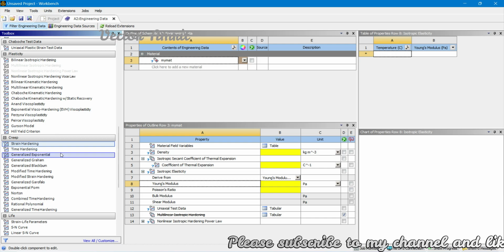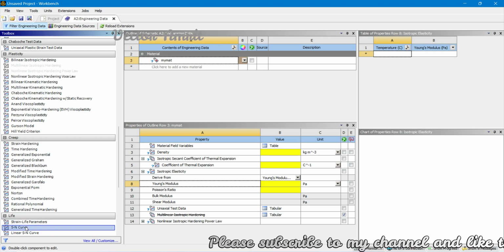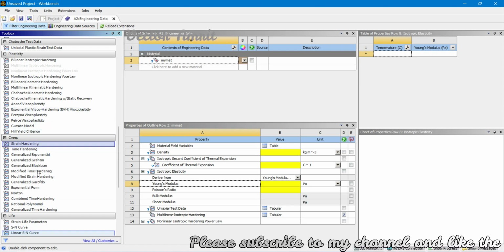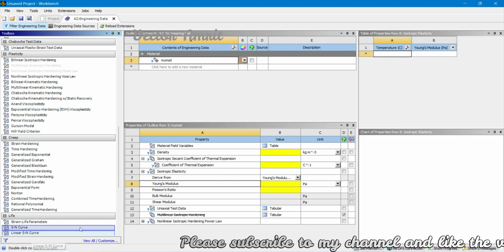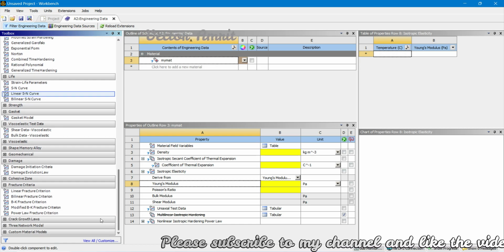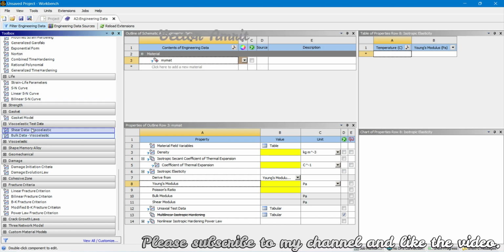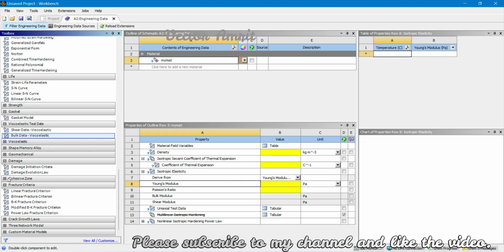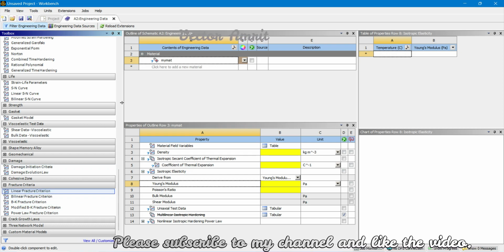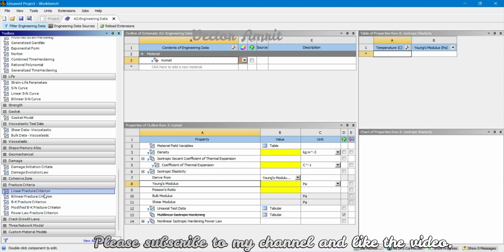Strain hardening is a complete name. SN curve is also a complete name, but SN curve linear comes under definition, as we have already seen previously. So here you have to enter SN curve as name and linear as definition. And some other things, for example, gasket model, this is a complete name. Shear data, viscoelastic, these are complete names. Then what else, like fracture, linear fracture criteria, this is a complete name. So here we don't have behavior and definition.